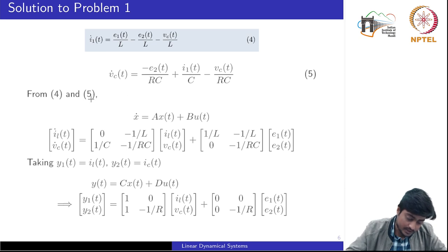After combining the equation we obtained in the last slide with this equation, we can write the linear state equation in this form, where A and B matrices are obtained, these two matrices. Y here is selected as the, in fact Y could be the state also, because if you recall the output equation is given by Cx plus Du.